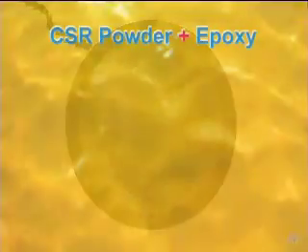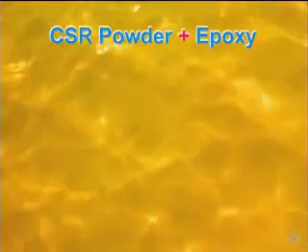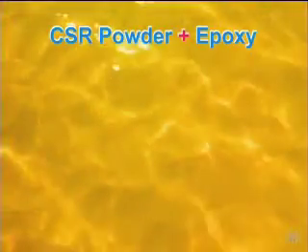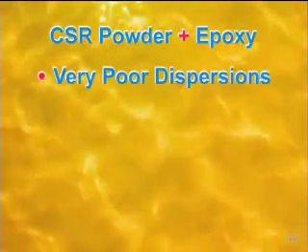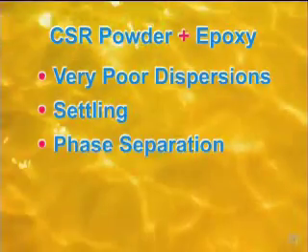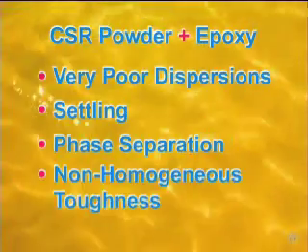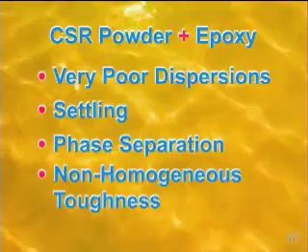Historically, attempts to mix CSR powder with epoxy and other thermosetting resins have typically resulted in very poor dispersions, characterized by settling or phase separation and inherently non-homogeneous levels of toughness.